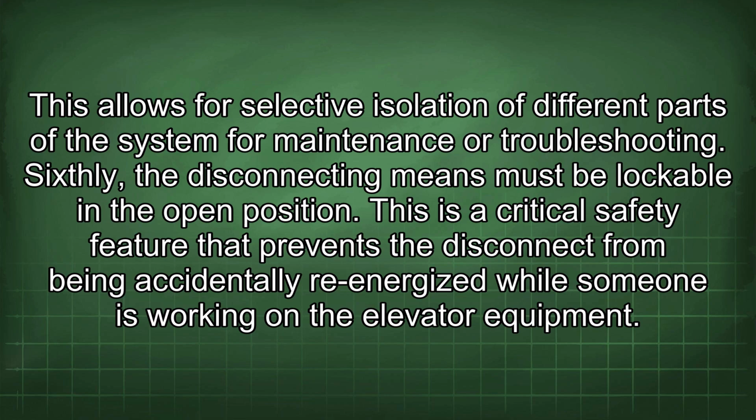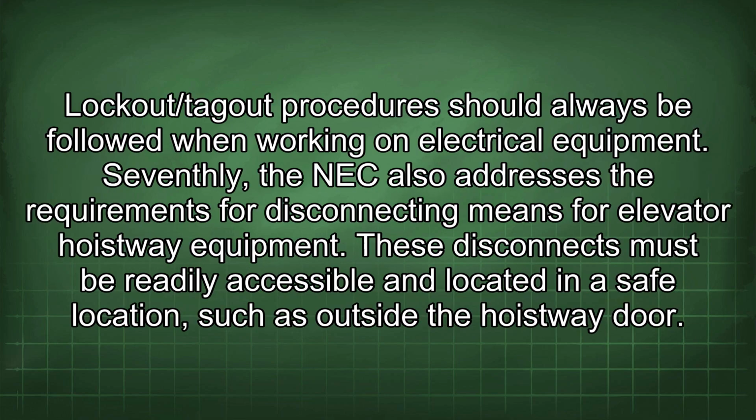Sixthly, the disconnecting means must be lockable in the open position. This is a critical safety feature that prevents the disconnect from being accidentally re-energized while someone is working on the elevator equipment.